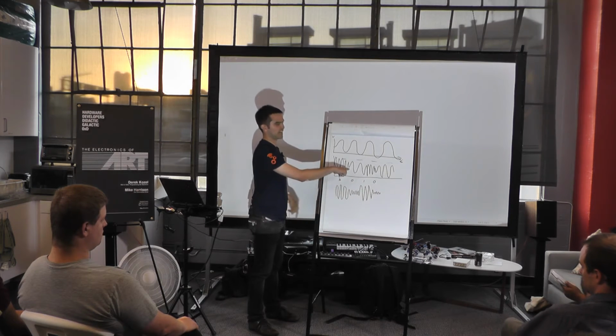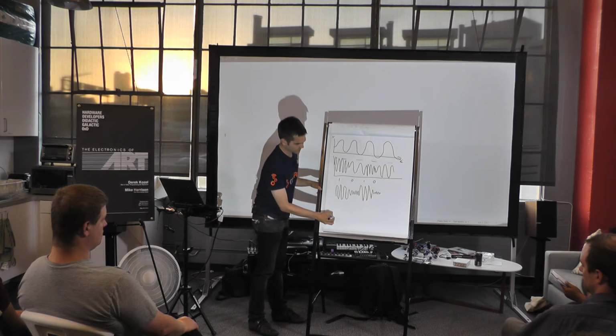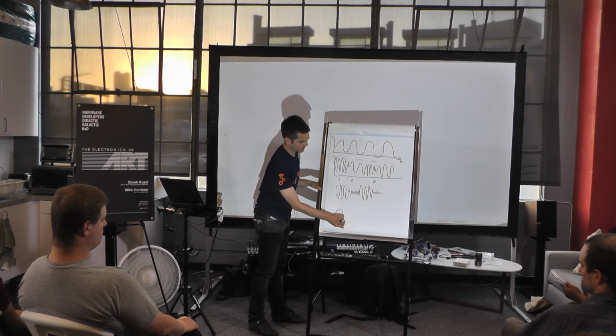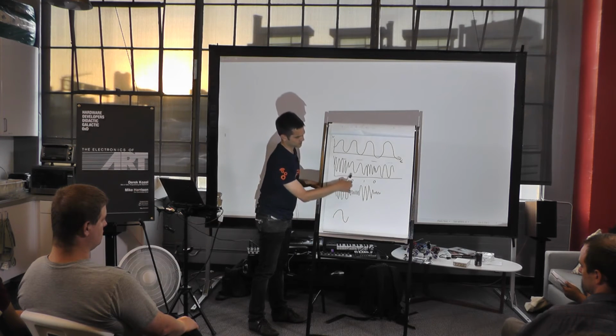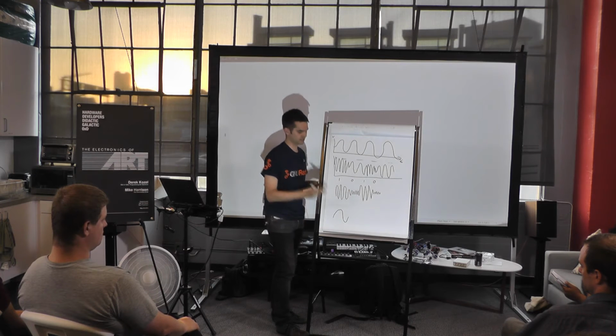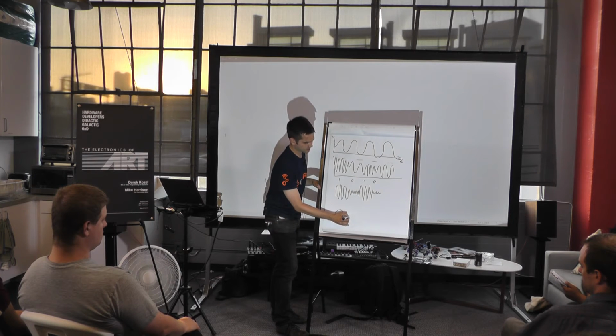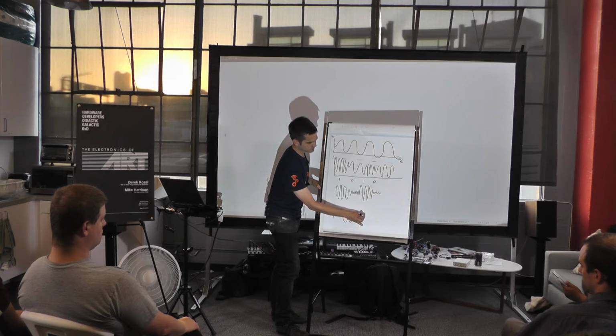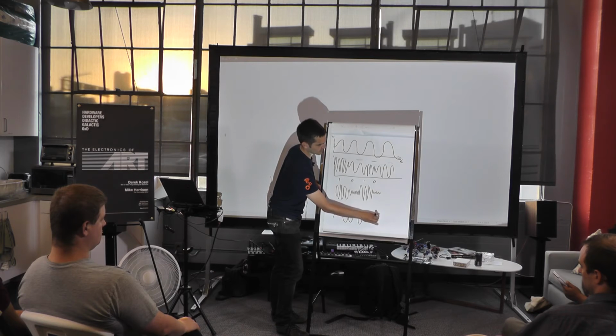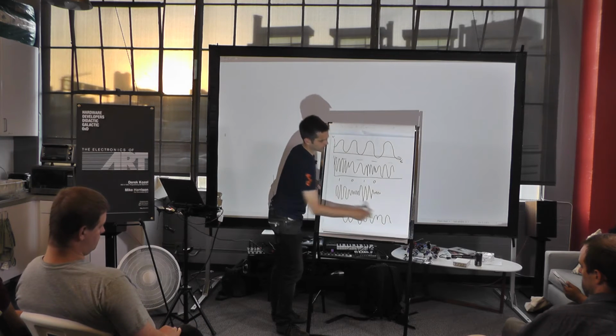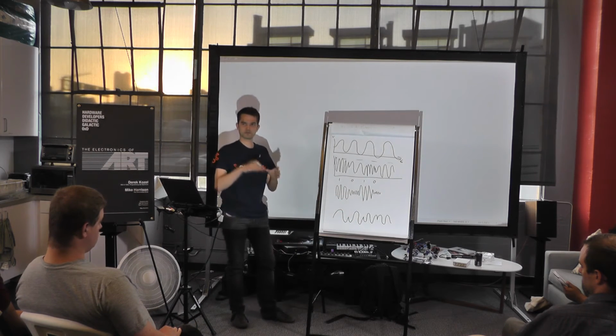Phase shift keying is what I accidentally drew here. So you have a sine wave that's going along, and then when it hits this transition point, and of course this depends on your encoding, but the most basic way of thinking about it is it changes phase in some way. So this would be a 180-degree phase shift, but there's a whole bunch of different versions. And it would do it again here, and again there. And there's different ways of doing these phase shifts.